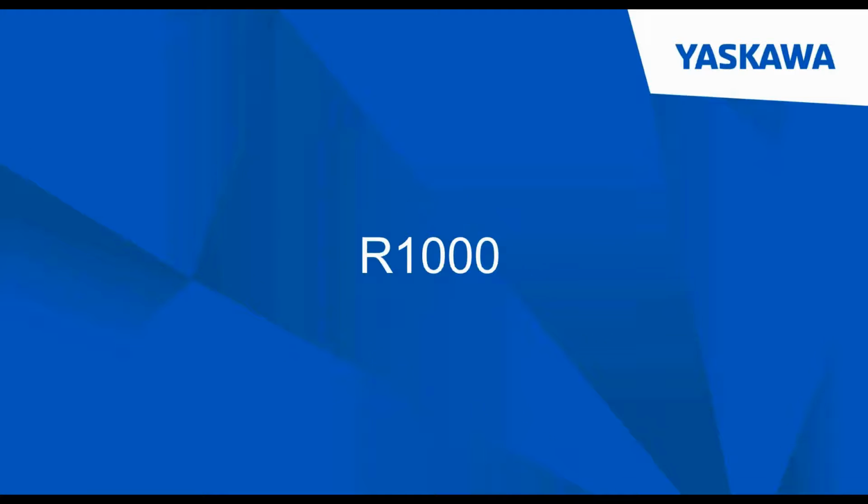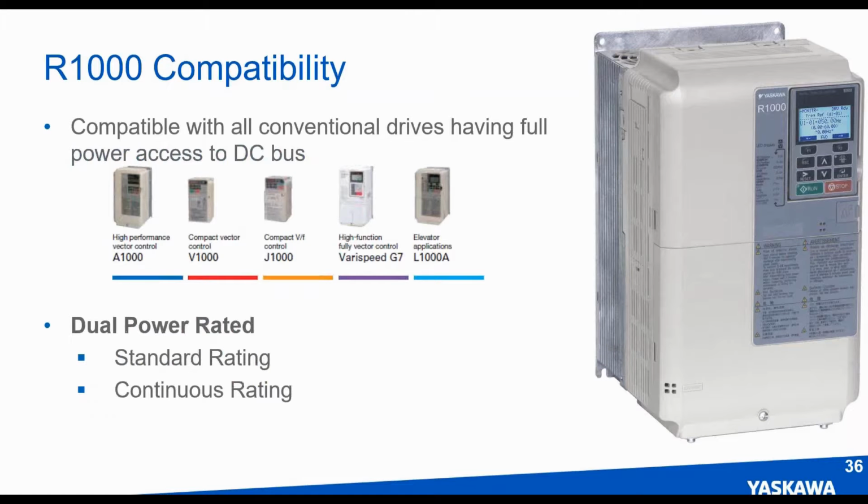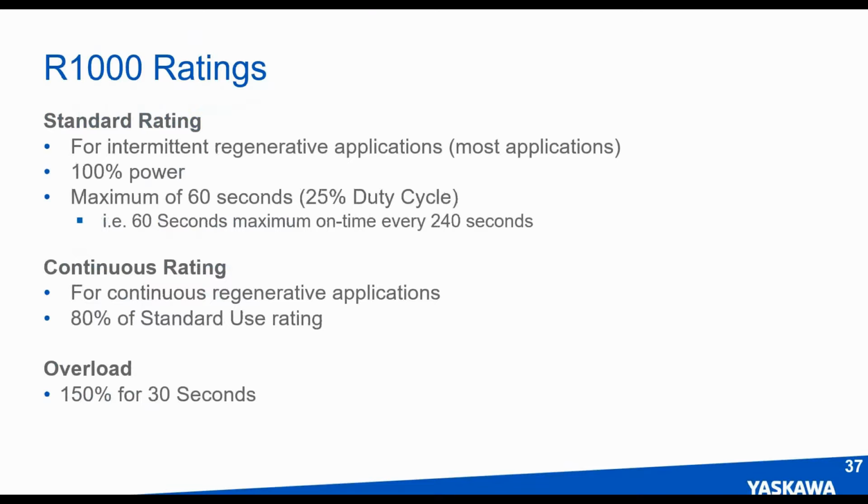Let's move on to the R1000. The R1000 can be used on any drive that has full power access to the DC bus. This means the A1000, the V, the J, the L1000, and the G7 are all supported by the R1000. The R1000 is dual power rated. It has a standard rating and a continuous rating. The standard rating is for intermittent regen applications. It has a 100% power rating at a 25% duty cycle. That's 60-second max on time every 240 seconds is what it can do for regen.